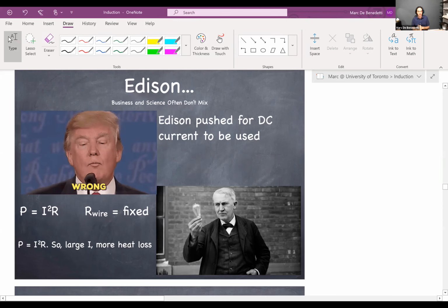It was a lower voltage, a couple hundred volts, kind of like what we have now in our house. The problem with that is when you drop the voltage, you increase the current. So sparks weren't happening because it was a low voltage and didn't reach the breakdown voltage of very many items. But the problem was, if two wires ever got crossed, or if there was ever a short in the circuit, or if you were screwing in a light bulb and your finger slipped and touched the terminals, there would be a very high current experienced when you touch those things.